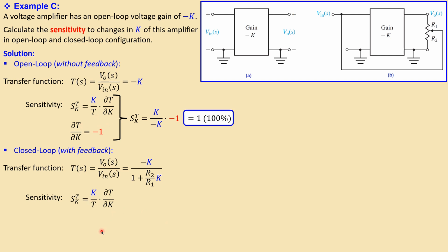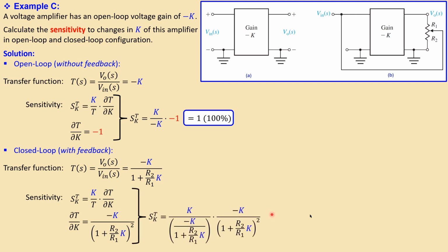And now we differentiate again the T, the closed loop transfer function, towards K. In this case, we need to use the rule for fractions, so the quotient rule, so that we have actually this one, so you square the denominator and then make the calculation for the numerator also. The result is this, and if you now add them up, you will get this expression.